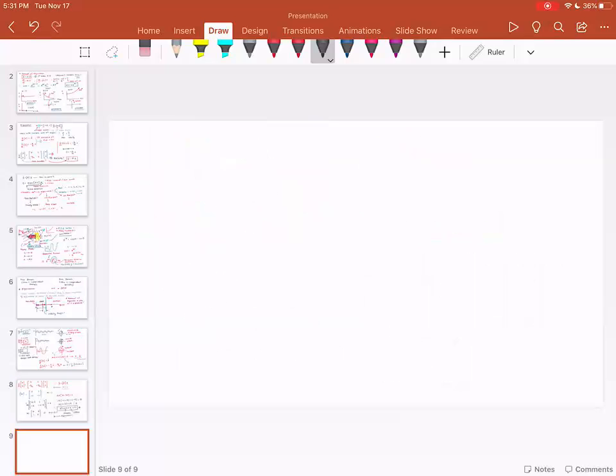So this expression can be solved with the quadratic formula. Let me write this down: lambda square plus c lambda plus k is equal to 0. Value of lambda is, looking at the quadratic roots, minus c plus minus square root of c square minus 4a k, a is 1, divided by 2. So this is the equation that we have.